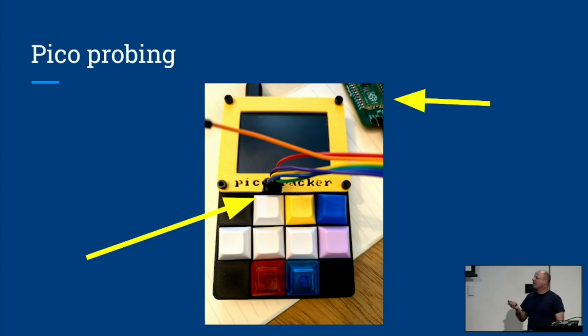Debugging, luckily the RP2040 comes with a way of being debugged by itself. You can actually use one RP2040 to debug another one. You just basically put some firmware on it that implements something called a Pico Probe. And so what you can see here is an actual Raspberry Pi Pico sitting there, connected with the little headers that I've got there on one of my debug picoTrackers. And it's a real pain in the bum to do that, to be honest.